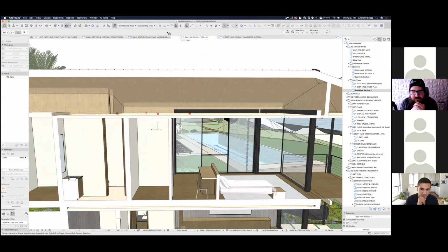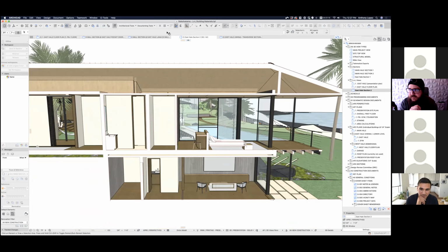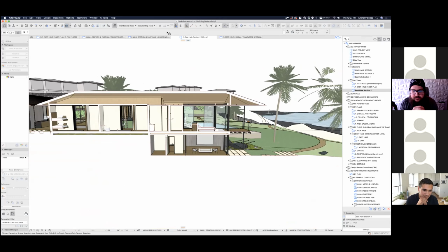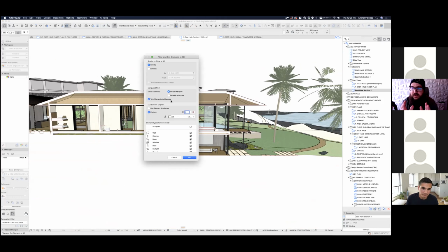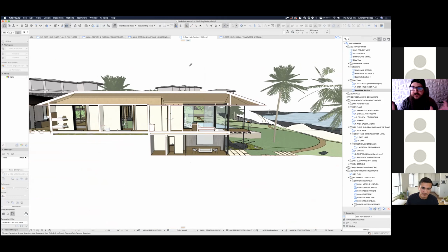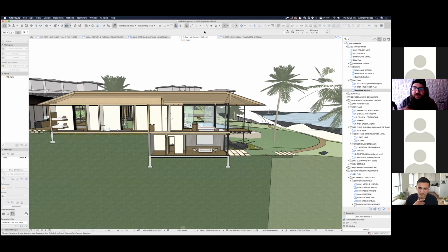And we certainly still retain the option to do this, right? That's the case with plan sections and the live model: we might want to scale this back in terms of level of detail that we're presenting early on, throughout early schematic design and even early design development. But understanding that we can take it to this higher level of detail, we can actually understand these intersections. I think one of the things that we've struggled with in some projects is getting the sections to clean up properly so that they have that sort of gray poche and white sheathing and finish all cleaning up. It's not exactly obvious what building materials are intersecting where, because we sort of over limited the building materials we were using.